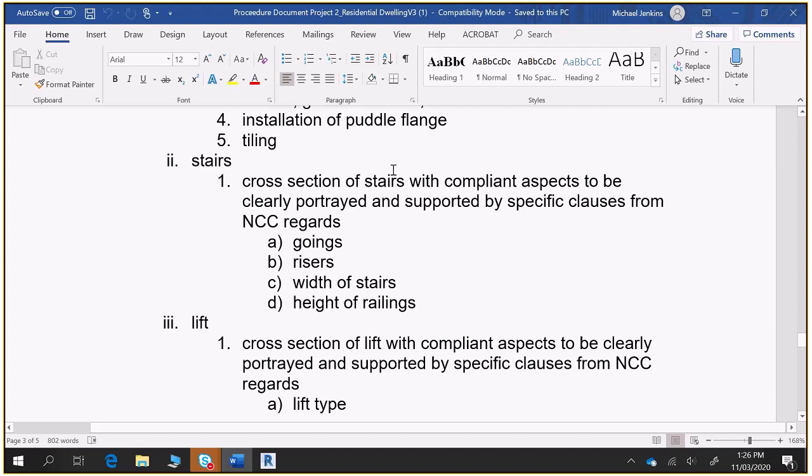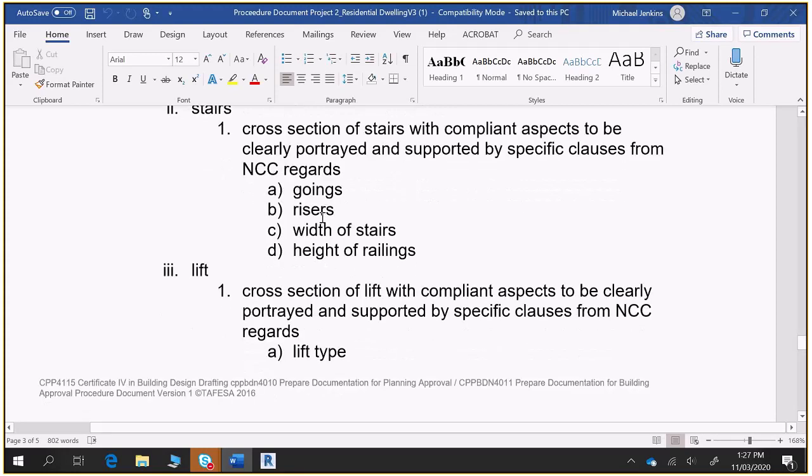Or another way you could do it is with your bathroom, you have no set down and you have no floor trap, and then all of your fixtures and fittings have overflow protection, and you have a preformed shower base. That's another way, not to do it as well. Once again, it doesn't work for disabled. So yeah, let's assume with this one that the reinforcing is far enough down our slab that we can do a quick cut saw in there, drop it 40 mil, chip it all out, and then redo it.